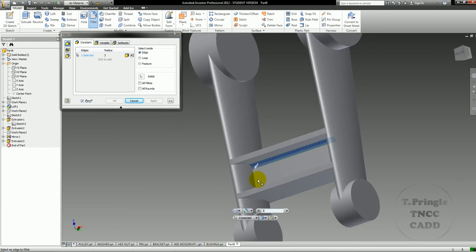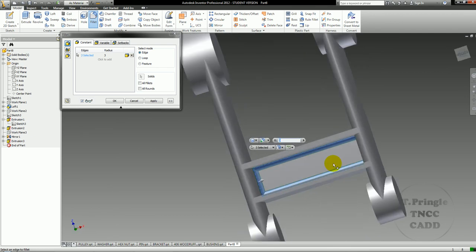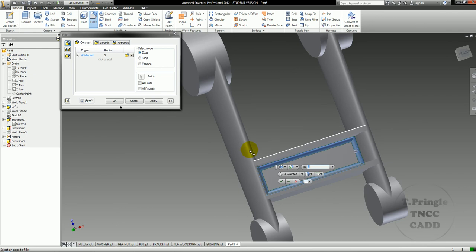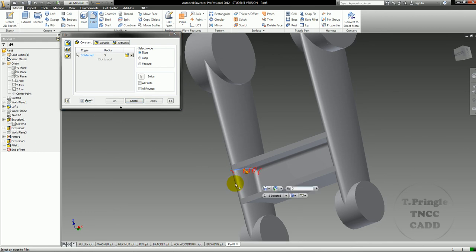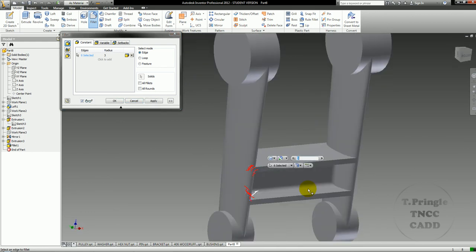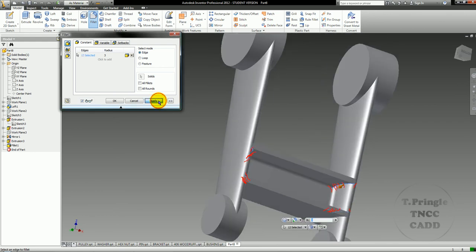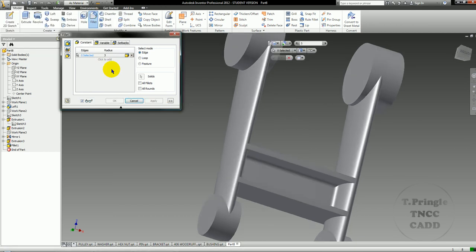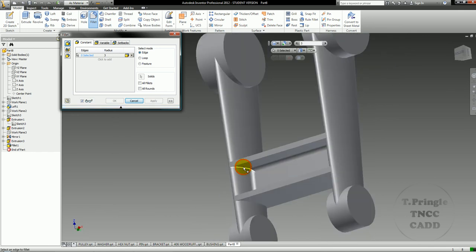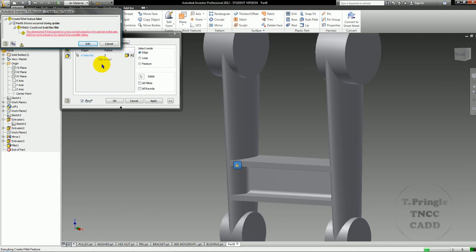and what I'll do is I'll do this line, and this one. I'll just give these 4 fillets in right now and see if that works. And if that works, I'll go ahead and move on to the next set of fillets. The next fillet is this one, this one, this one, and this one, and I'll apply that. Okay, that's the one that's failing out. So in an effort to try to figure out which one is failing, I'll just go ahead and do this shape and this shape and hit apply. That's where the failure is going to occur.